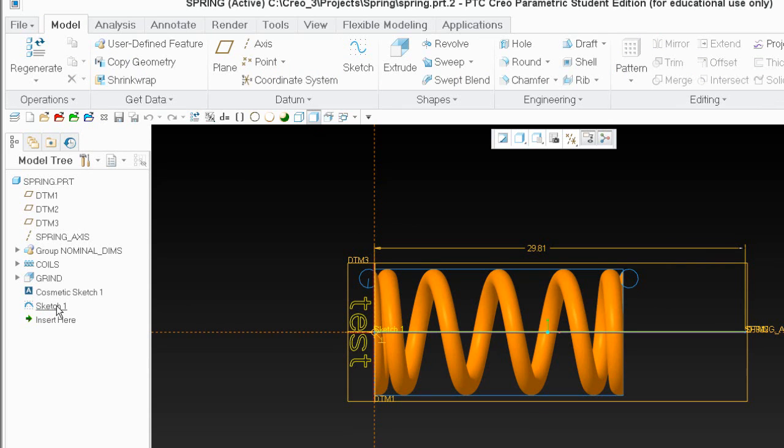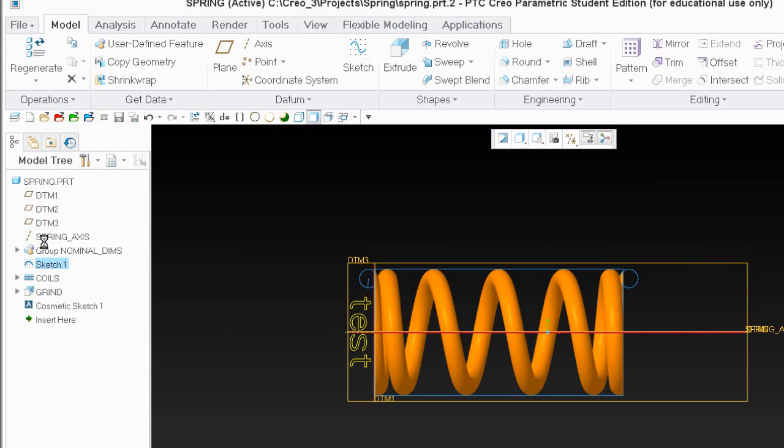And how I'm going to do that, I'm going to place it before all the geometry. Did I regenerate yet? Okay. Oh, wrong place, up here. So it's right after the axis, before any geometry is created.